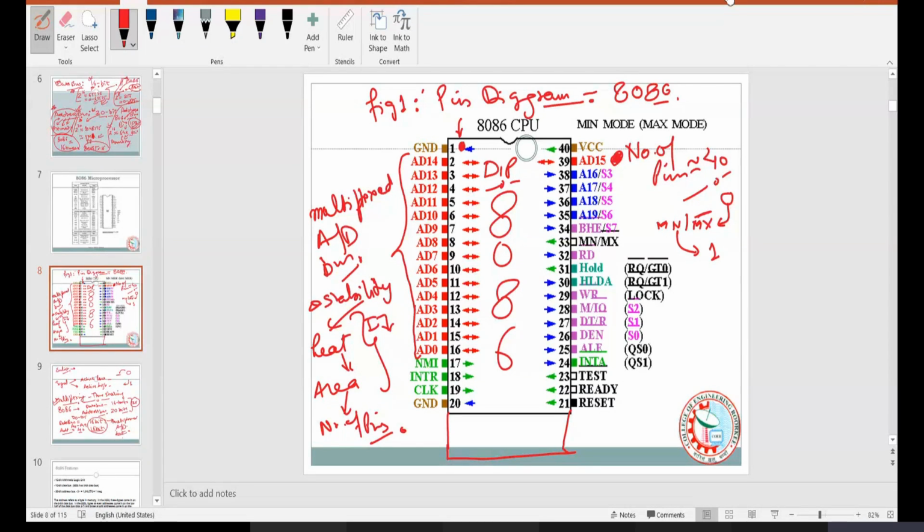But yes, we can adopt some strategies so that heat will be dissipated by the surface of the microprocessor. So what happens with the gel pad? The gel pad takes the heat and absorbs it. The heat sinks connected to it take that heat and dissipate it in the air. What fans do is provide constant air so that it cools off along with the heat sink. So there are various strategies you can adopt. Even liquid cooling is coming, but that is not very successful in the domestic setting, because of the very small size, and moisture remains in the circuit that can short it.